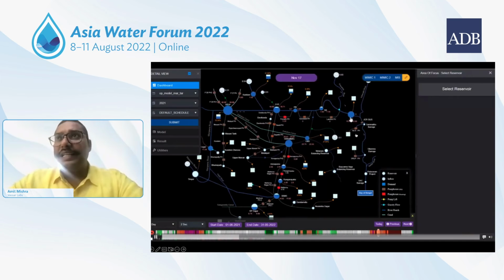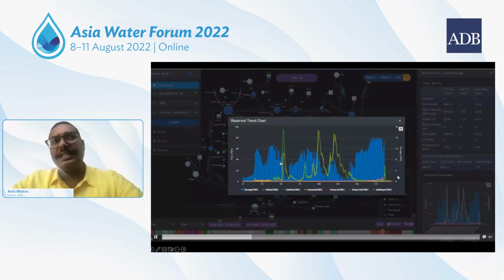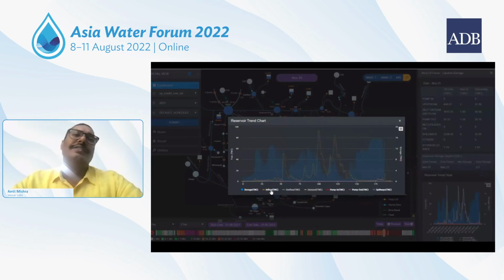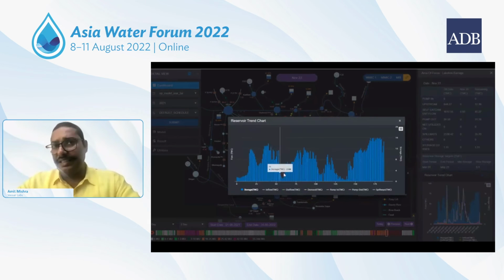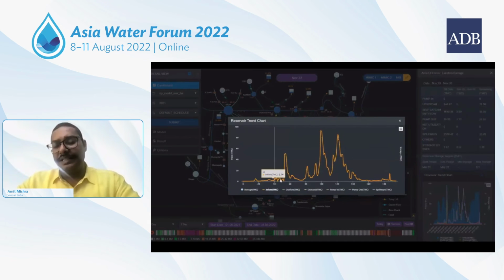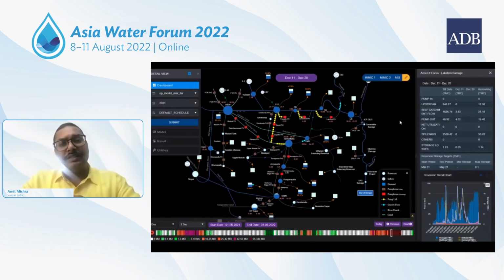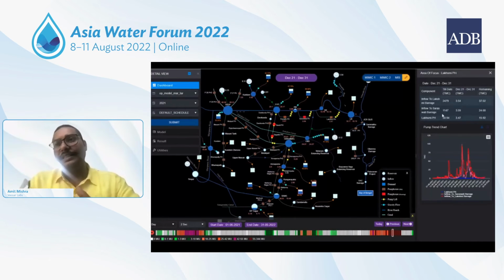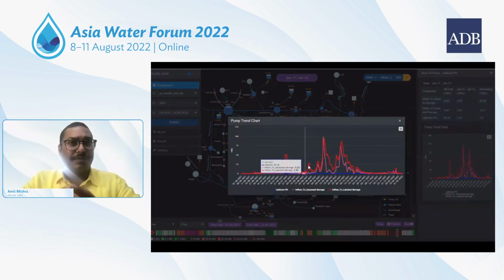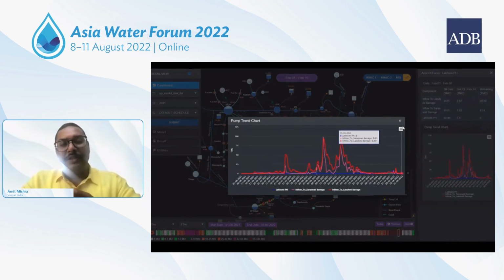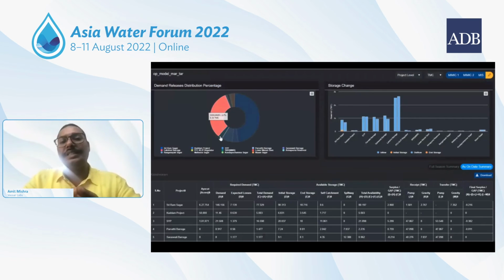In this area, we have to fulfill the irrigation demand and other drinking water demand, industrial demand, and there are multiple reservoirs. So by understanding the current demand of agriculture and industry, all in near real time, using satellite data, your ERP data and field data, and then understanding the current water levels and your weather, this gets automated, and it suggests how you have to operate your reservoir in real time with your lift mechanism so that your production capacity is maximum and electrical consumption is minimum.